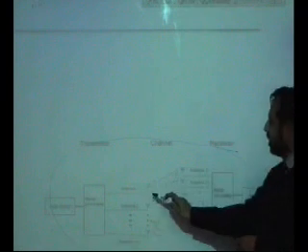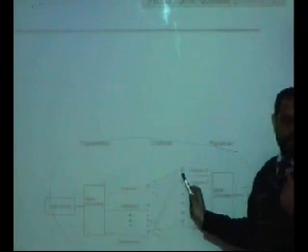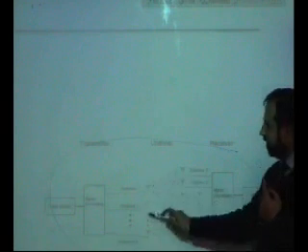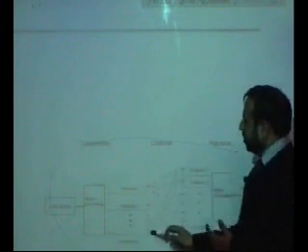Why is it such an attractive solution? The reason is that if one transmitter can, let's say, transmit 1 megabit per second, and you have 10, you can effectively increase the data rate. It's all about data rate. You want more and more data rate. EDGE technology, GSM technology and 4G technology are all about putting more and more data in the same channel. This is how it is being done: the same mobile phone will have multiple receiving antennas, and the base station will have multiple transmitters. Every transmitter throws different bits, and you then have to recover them. So this is the MIMO system.